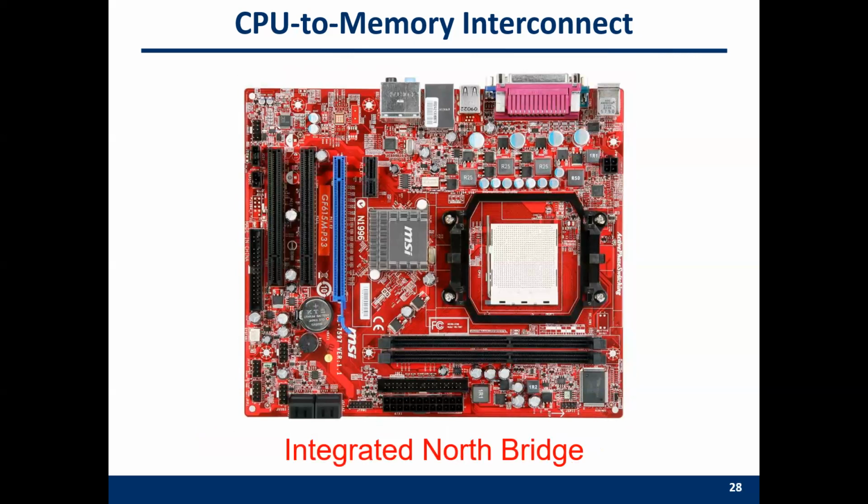For some other high-end CPU, you have a very large CPU here, and the memory controller is integrated into the CPU. Then you do not have a so-called front side bus anymore. The bus is integrated in the CPU itself, so it's easier to achieve higher frequency. The memory controller integrated in the CPU can talk to the memory here. And you also have a south bridge.